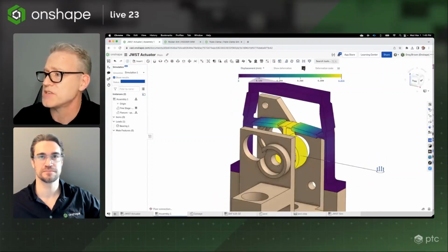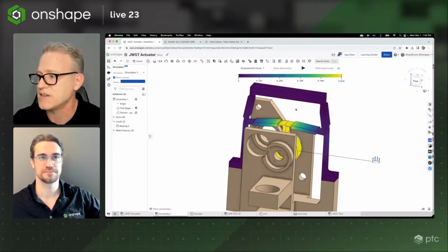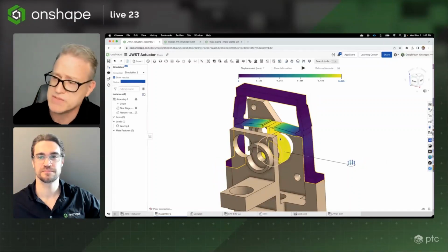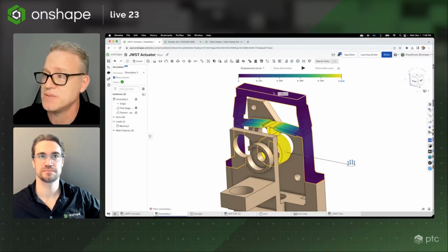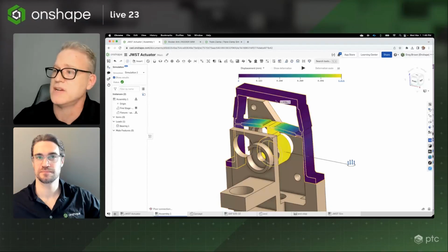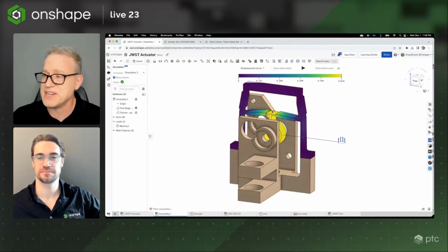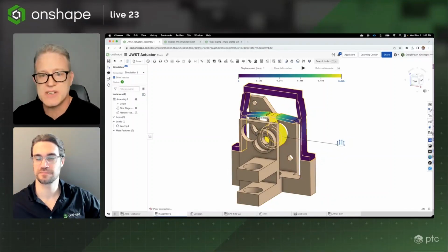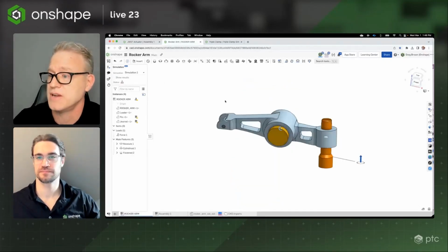And the displacement's interesting because the real beauty of this mechanism, getting back to some engineering geekery here, is that a small motion here of about 0.6 of a millimeter will result in an extremely small motion at the top here, which is actually what's actuating the part of the mirror. So we're getting like a 50-to-1 gearing down, essentially. But enough of that. Really, what's been interesting is how easy it is for me to get into this and start looking at how it all works in a design sense.